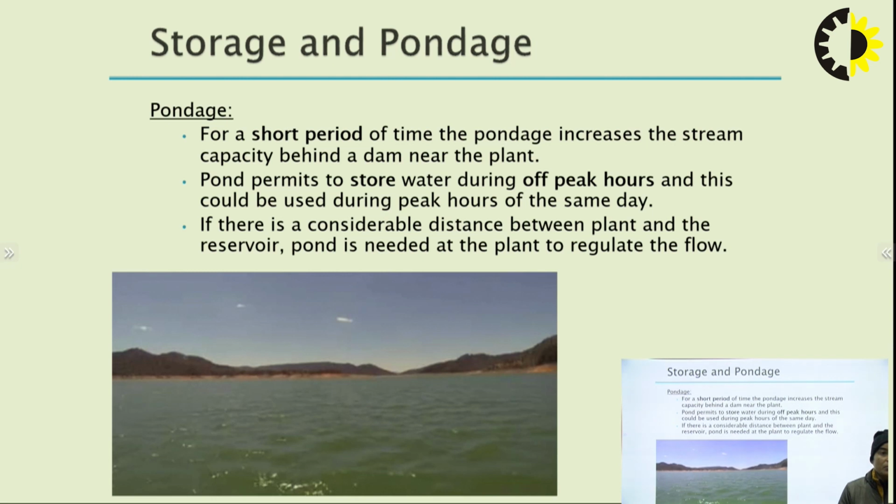So pondage permits storing the water during the off peak hours, and this can be used during the peak hours on the same day. So if there is considerable distance between the plant and the reservoir, a pond is needed at the plant to regulate the flow.